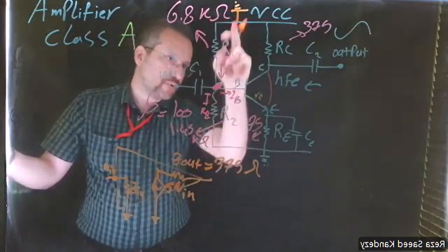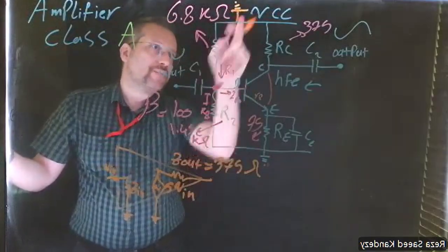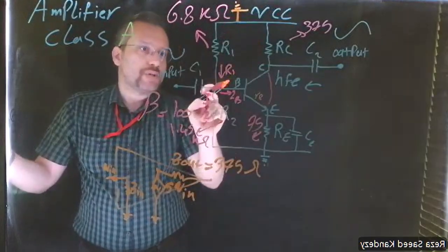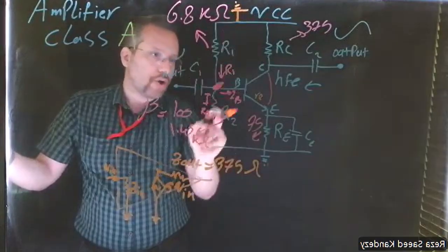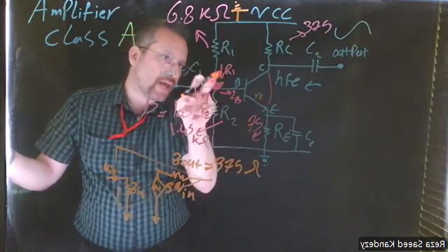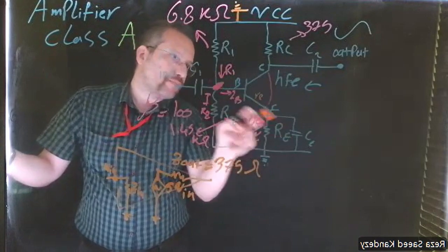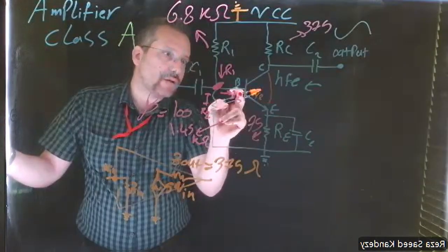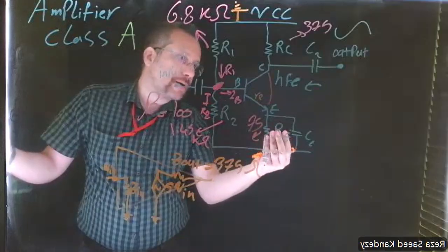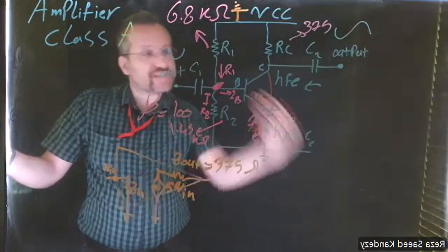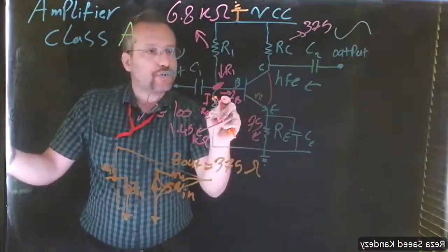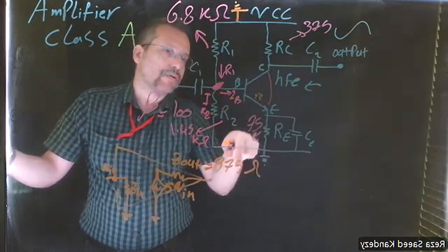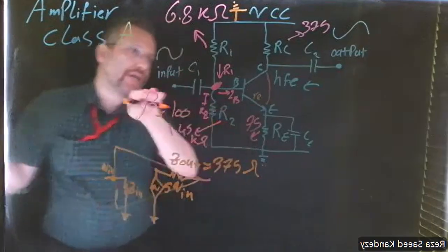So if you look at the circuit, that means we have R1 between the input and the ground, R2 between input and the ground, and here RE between input and ground, but this is not RE. We have a BJT in the middle. We have to transfer the RE to the base. So these are the parallel resistances that create that input impedance.